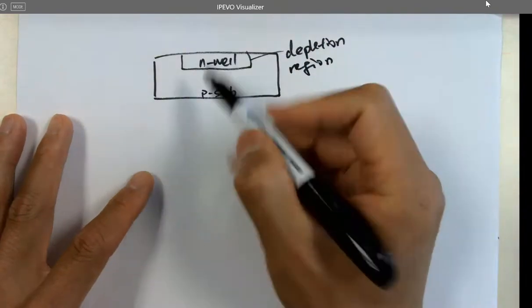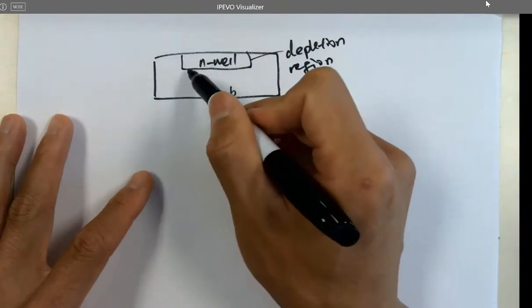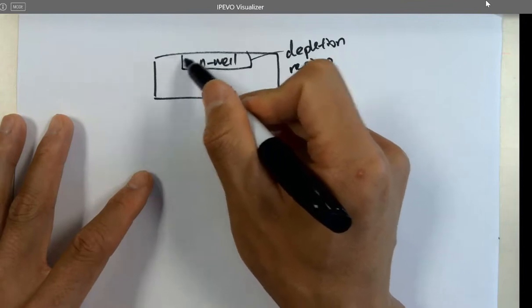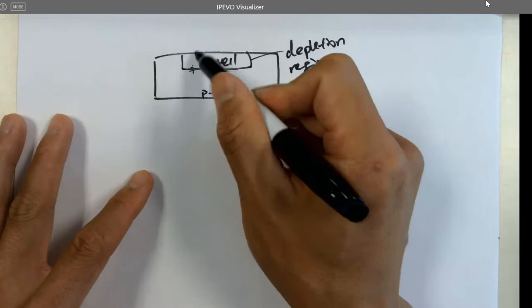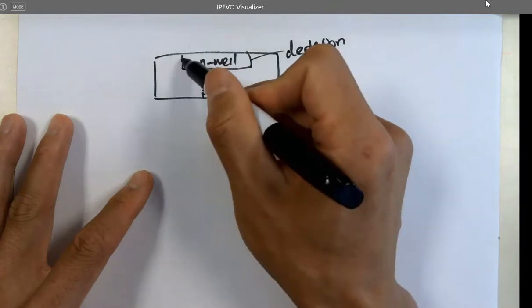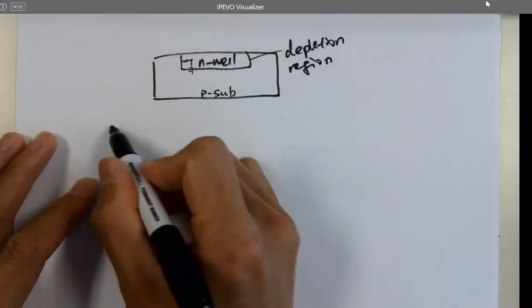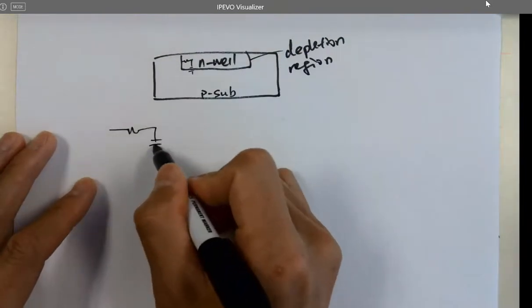And that's cool. The depletion region is going to form all these parasitic caps, remember? Caps. And we split the entire N-well into all these little R squares. So if you model this as an RC circuit, it looks like this.